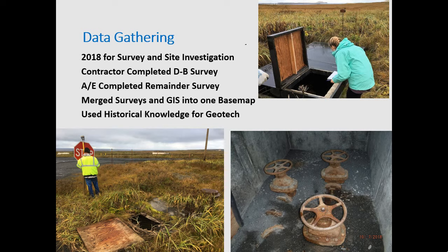So then once we got all this information, we had the design build contractor with the survey, we had our survey, and we had GIS from the owner. And we were trying to merge all of this. We spent a month and a half between the different databases. There's the survey control discrepancies. Again, it goes back to the utility record drawings, and trying to merge it all was not as fluid and seamless as what we had hoped it would be. But in the end, the owner wanted this entire map of what their system is out there of all the utilities. So that was one of our tasks.